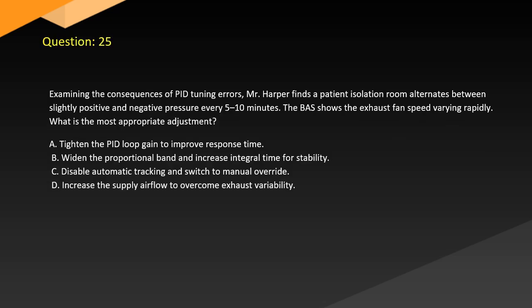Question 25. Examining the consequences of PID tuning errors, Mr. Harper finds a patient isolation room alternates between slightly positive and negative pressure every 5 to 10 minutes. The BAS shows the exhaust fan speed varying rapidly. What is the most appropriate adjustment?